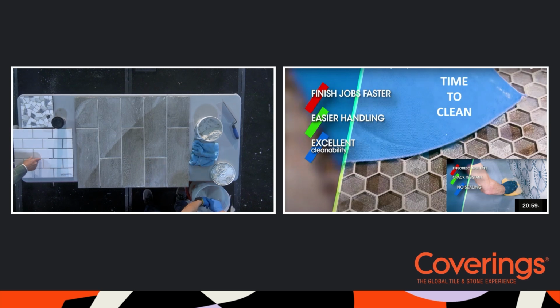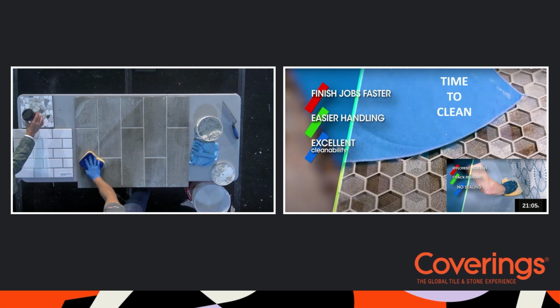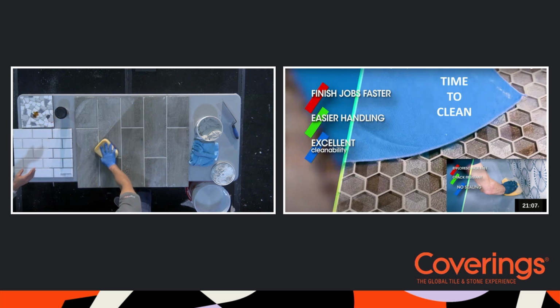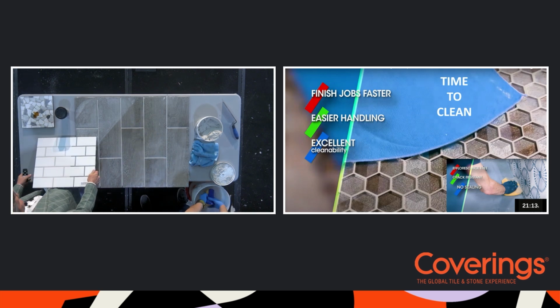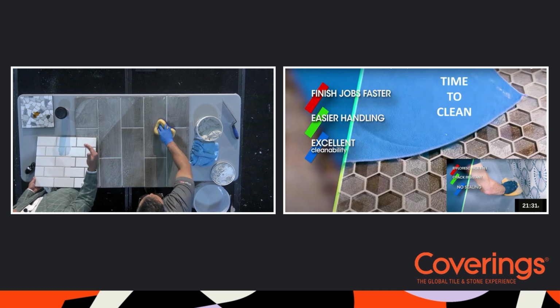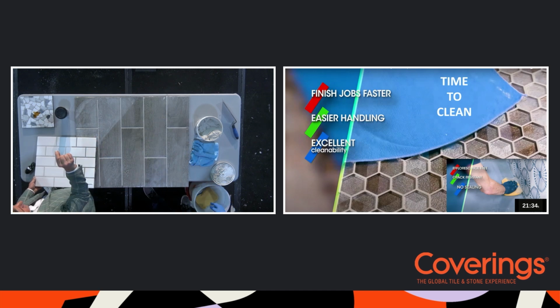Now, I want to show you this panel, and while I show you this, I'm going to pour some coffee just to show everybody, yes, it is stain resistant. And on this panel, I don't know if you can see it, kind of move it over here. Here you have the darker color is the original grout. The lighter color is a top grout. And the joint depth is only about a 32nd of an inch. So because of its adhesive properties, we can use it to re-grout. We can put it over cement grout, we can put it over epoxy grout. All we need is that small 32nd of an inch. And now we have new grout.